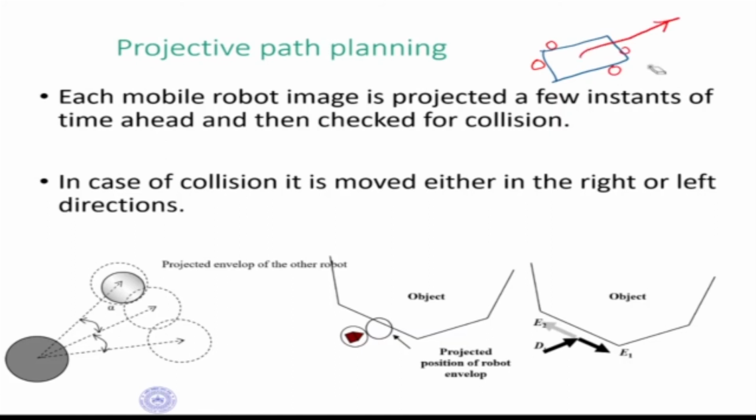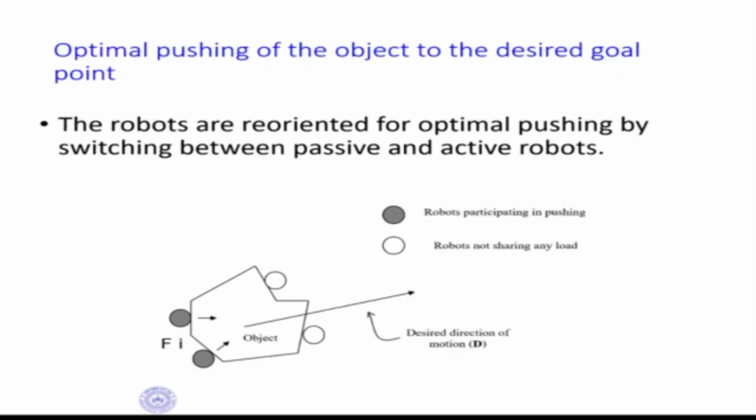What I must do is reposition this robot such that the robot pushes in this direction now. Otherwise it won't go in that direction. So the robot has to change its position again and have a new path plan to push it somewhere else. So for example, in the object here, the robot sits here and pushes it and applies a force in this direction. So what we need to do now is reposition the robots, and after repositioning, we can push in some direction.